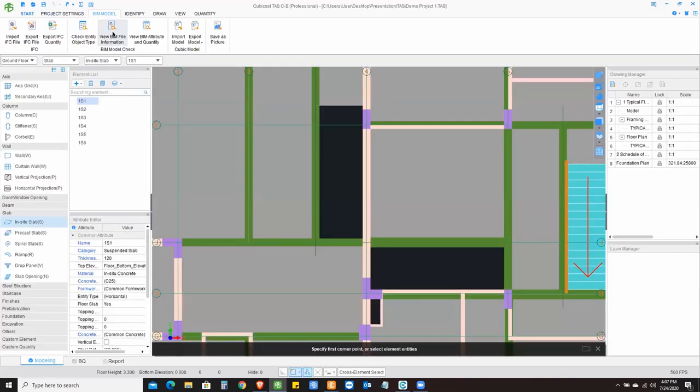Well, okay, so when it comes to importing a BIM model, we have got import IFC file. That is basically the shareable file between two BIM software, as we know. But then we also have an option for a Revit file, .rvt file, and that Revit BIM model can be imported if you go for another extra module. So that is in another premium package. It's not available with my software at the moment.